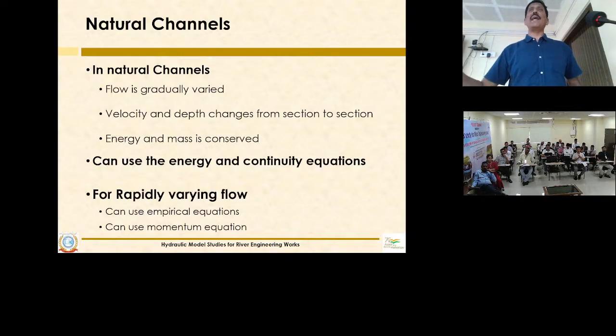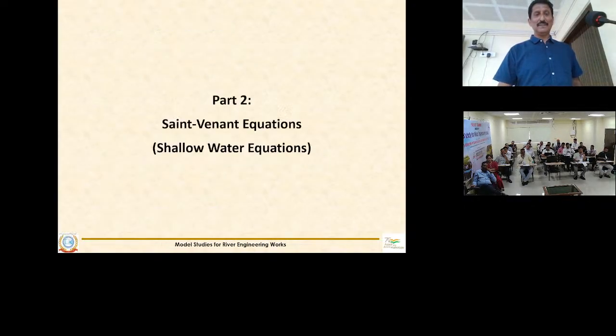But in some scenarios like bridges or some junctions, when the flow changes, that is accounted for by using the momentum equation. It has an explicit choice whether you have to go with the energy equation or the momentum equation. When you compute the bridges, that option will show you which scenario you have to develop. And secondly, for the sudden changes, we have to see and adapt. So basically in this HEC-RAS we will be using the energy and mass conservation.